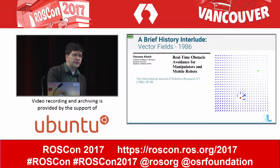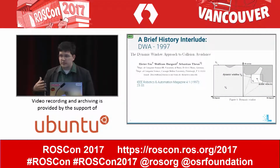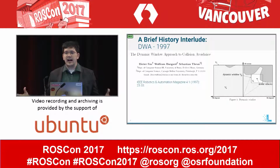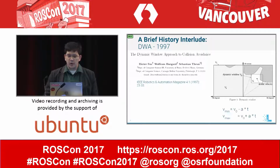But if you're very far away from the goal or very close to one of the obstacles, the force vector can be immeasurably high. And so as a result, there are commands that you really can't perform given the acceleration limits. And so that leads us directly to the DWA algorithm, the dynamic window algorithm. This came out of a paper in 1997. And the idea here is we're not going to look at the entire search space. We're just going to look at a small dynamic window around what the current velocity of the robot is. And the size of this window is dependent on both the acceleration of your robot and some time constant.